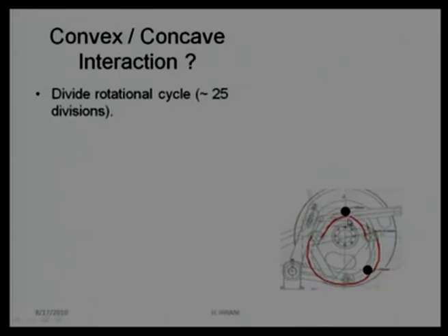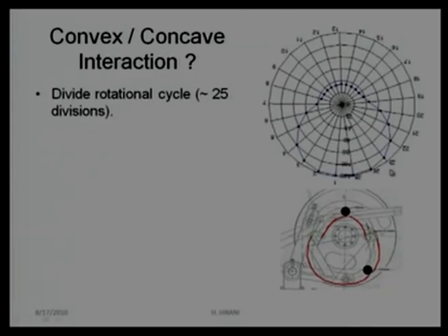As there is some clearance, it moves from this point to this point. This convex shape will come in contact with the concave shape that is shown over here. This is a convex, this is a concave. So, one cam roller follower is generating convex-convex as well as convex-concave contact in one complete rotation. We can find out the radius of the cam. Initially this is the convex shape, and after that, as this radius acts, it will be a concave shape radius.